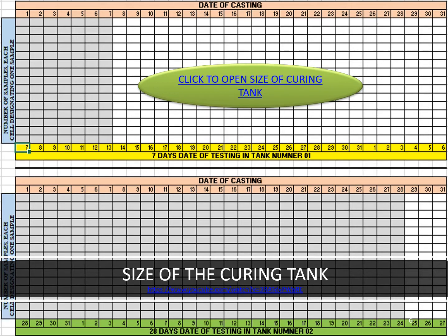As far as the storage condition is concerned, this is the bandwidth of 7 days storage, indicating that the cubes are tested at 7 days, because at any point of time this will be the occupancy of the cubes for 7 days strength, and the tank below will be for the 28 days strength. So the area covered by 28 days strength and the area covered by 7 days strength will vary depending upon the quantity of concrete poured in the project per day.